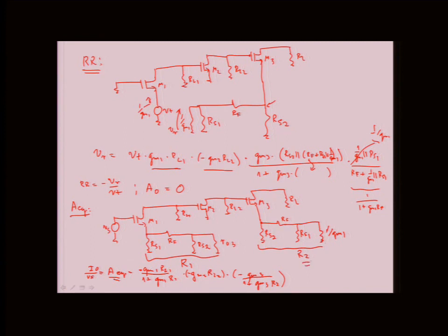So this whole expression is really just R2, right? So if you do some approximations, you'll be able to see that this is really minus RR times RL over RS1 in parallel with RS2. And so this could be your essentially A infinity. Or minus that is A infinity.